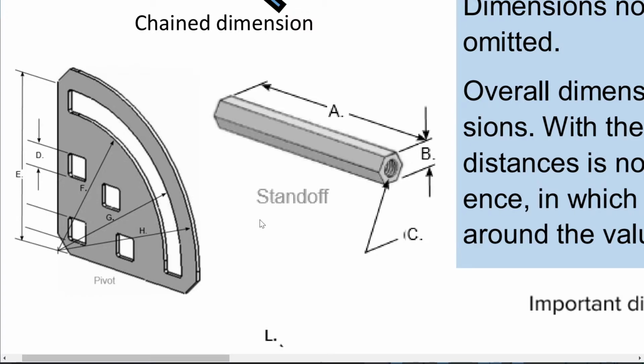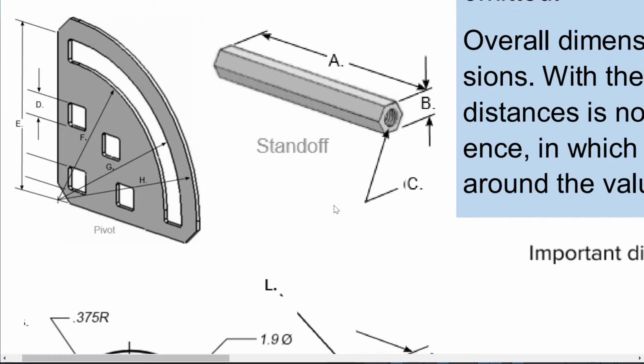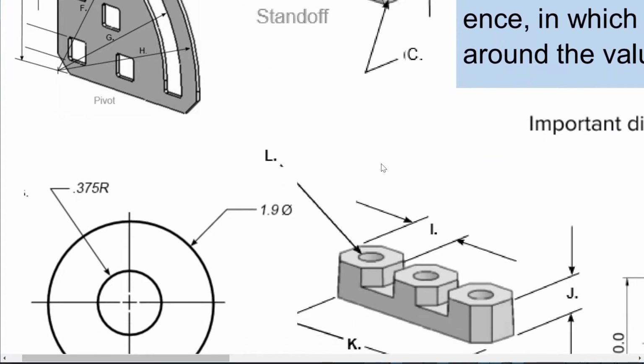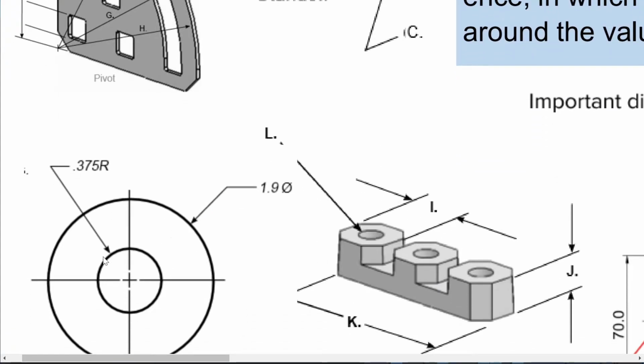Now, leader lines are for when we want to talk about things, and so we're not going to dimension that. We're going to draw these lines. Typically, we want to draw them at a steep angle. See how in both of these cases, I would draw them at an angle other than 45 if it were me. 30 and 60 is ideal, but if you can't do that, then you draw it at some angle.